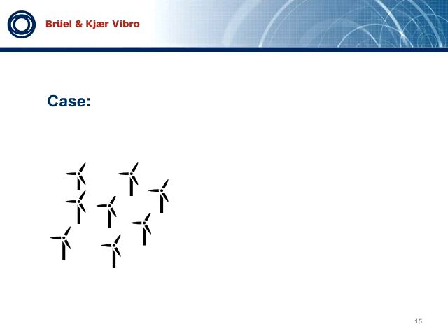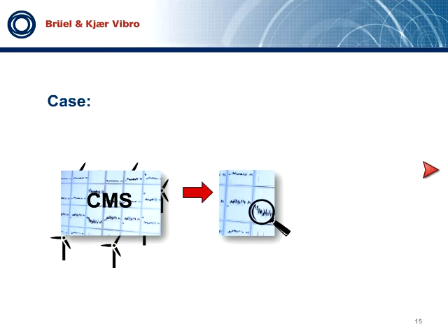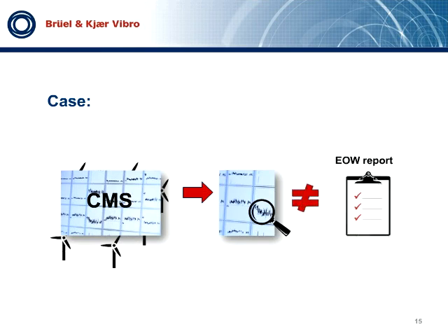So one case here. A part comes out of warranty. CMS is retrofitted prior to the end of warranty. Several turbines showed what appeared to be a fault signature. But when we went through the end of warranty reports, they stated no anomalies. So we went through all the borescope pictures, and we were comparing that with the vibration data.